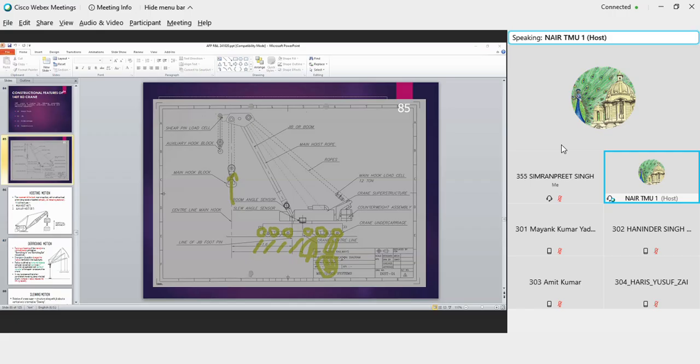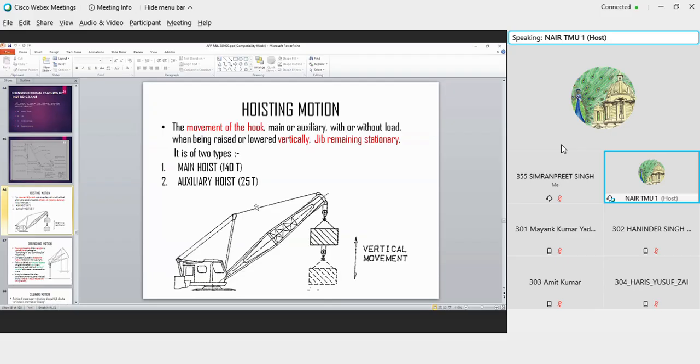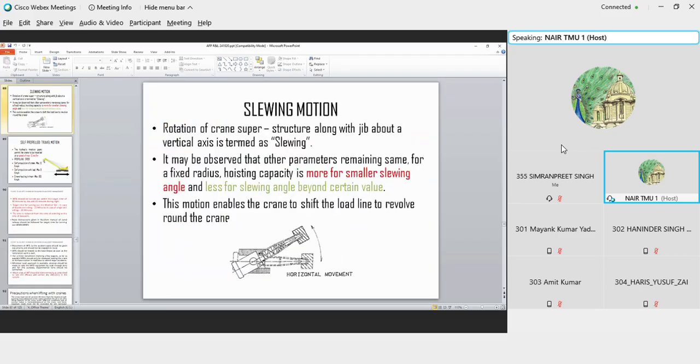So you will dig inside the earth, you will put in ballast inside it, and you carry something called wooden packings. So you will place wooden packings on top of this surface, and then the prop will come and sit on this wooden packing. So you're basically propping up the crane. And when a 140-ton crane comes on an accident site, the maximum time is taken in this propping.